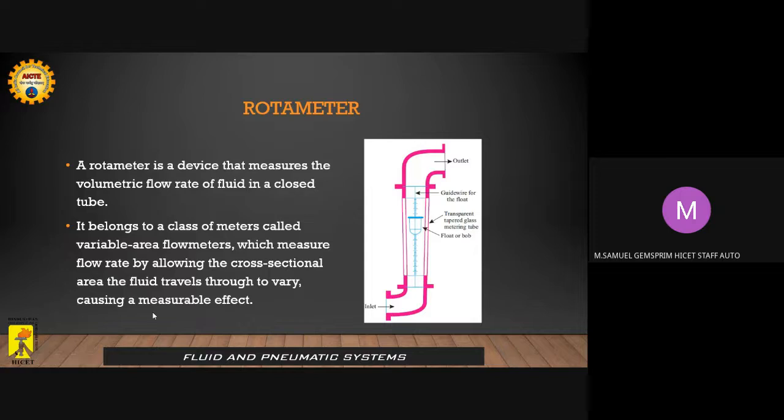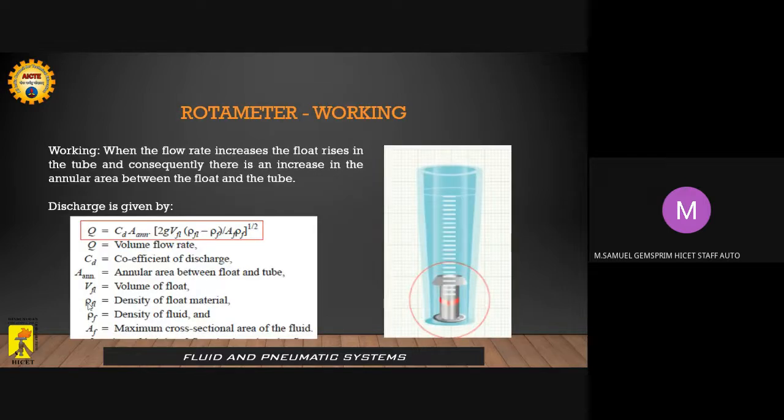Next, we are moving on to the next important equipment known as the rotameter, or sometimes the flow meter. The rotameter is a device which uses the pressure of the fluid to make a float move up and down on a calibrated or graduated scale. Thereby, the flow can be easily measured. It is a simple but very effective piece of equipment.